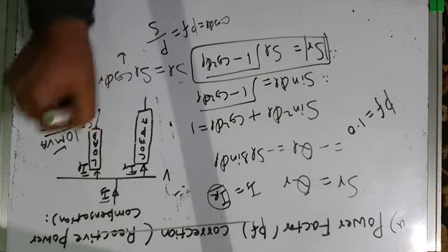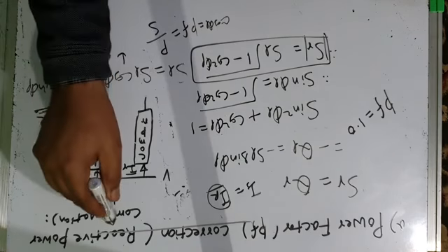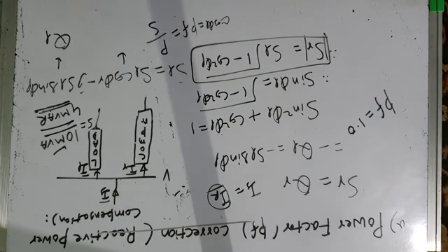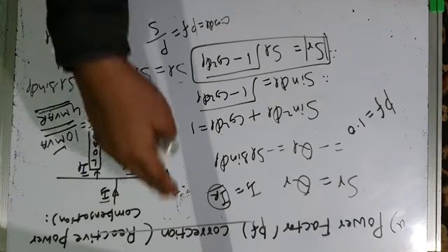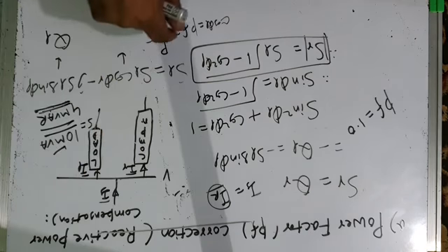So therefore shunt compensation decreases the current drawn from the source, and hence you don't need to increase the MVA rating of generator, transformer, transmission lines.